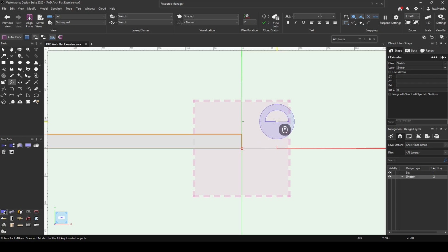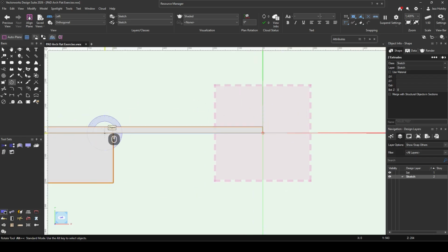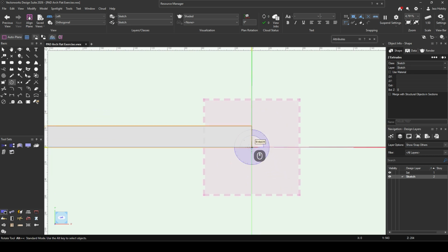Now it has what we call a 2-click mode. The first click designates its pivot point, so where it starts rotating from, and the objects will rotate in relation to that pivot point. So if I click once there, which is the bottom edge on the floor, the second one is the edge that will rotate. I could click off this edge here, but I would have to line the base up, because this will be offset. This edge won't line up to that.